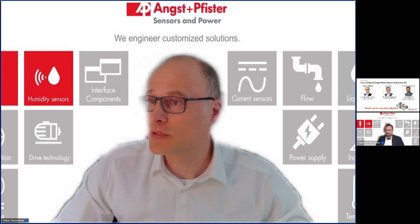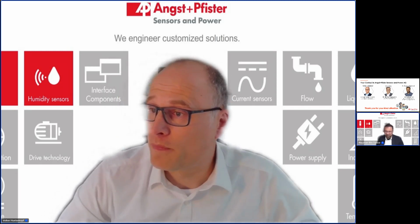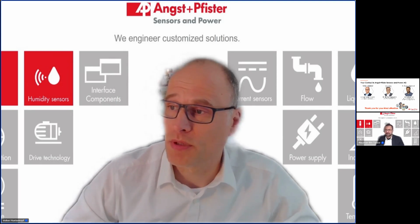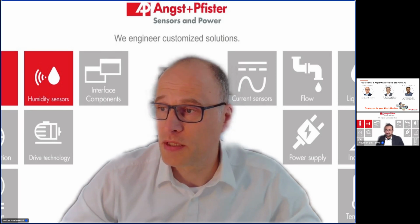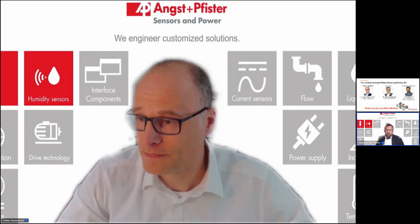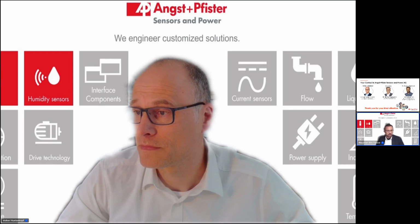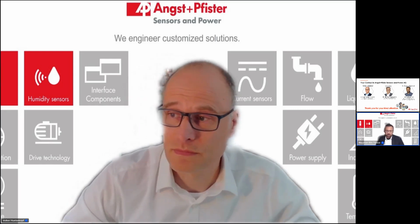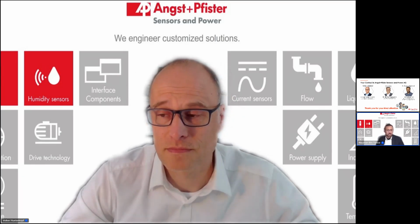Okay, so I'll just pick some. So Nauman, why is the portable paramagnetic analyzer that we offer not being operated with battery power? That is more related to the working principle, the paramagnetic. It's a very power consuming principle, so it needs a lot of power. And one of the reasons is that the sensing principle is influenced by temperature.